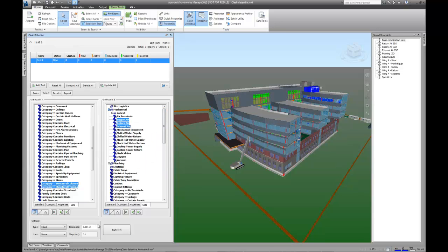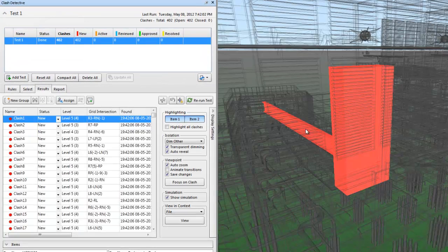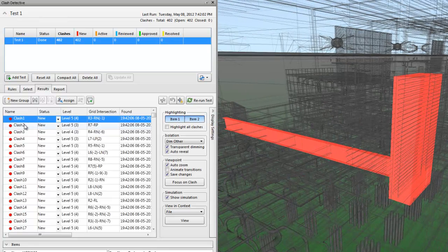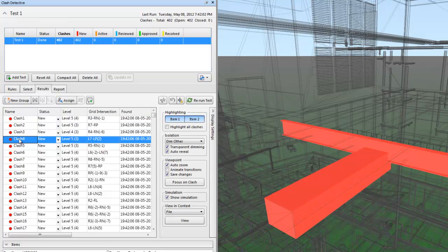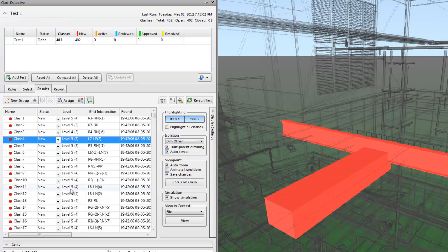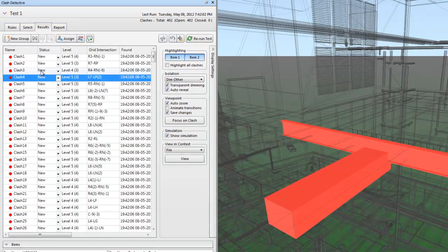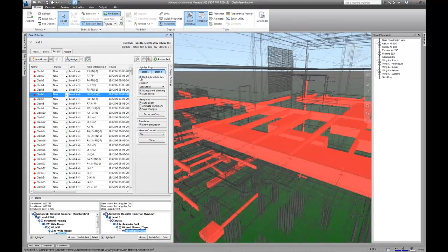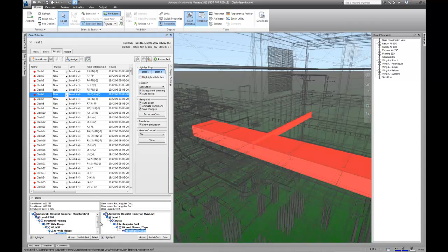The project model can then be analyzed for cross-discipline interferences, be they conflicts with HVAC systems and the steel structure, or adequate clearances around the fire protection sprinklers. Here we can see that a macro-level clashing of the systems and project components can be done. We can also follow our work breakdown instructions and leverage the area and zone schemes established for executing the work. We see how issues can be visualized more clearly, reviewed in a collaborative way, and assigned for follow-up actions.